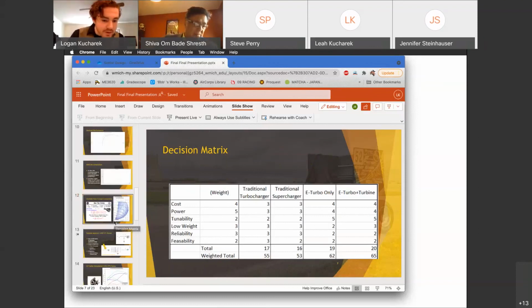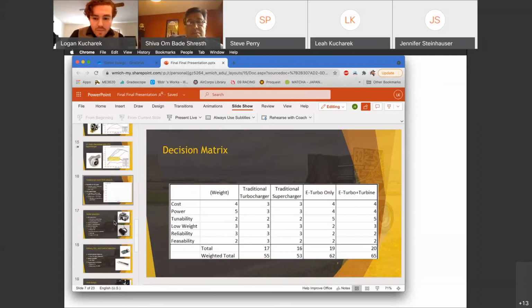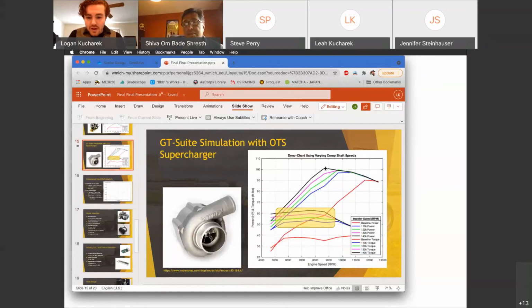One slide in particular here, this one, where you can see the peak power as the impeller speed is increased, moves backwards. But theoretically, we could ride this black line at 140,000 RPM all the way up, and then we could start tapering back impeller speed and ride the peak pretty much all the way across. Yeah, so you could make a lot of gains in terms of drivability for the different driver skills you talked about. Exactly. Anyways, great project.